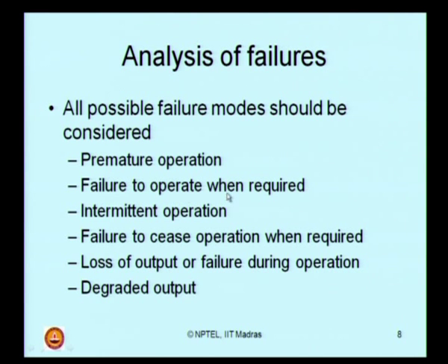Failure to operate when required, for example, you have a pressure relief valve which will open and release the pressure when the pressure inside a vessel reaches, let us say, 10 bar. Now if the pressure relief valve does not operate despite the pressure reaching 10 bar, then I can say failure to operate when required.